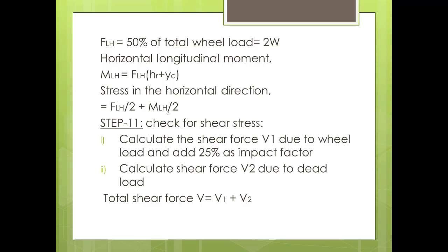In step 11, we have to check for the shear stress, which is one of the very important steps. We calculate the shear force V1 due to wheel load and add 25% as impact factor. We already studied impact factor earlier. In the table, I have already mentioned what impact factor you have to take.